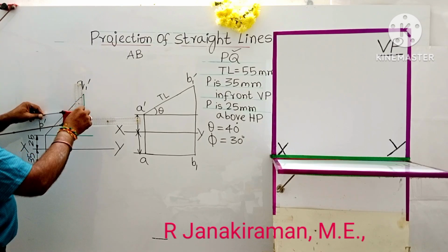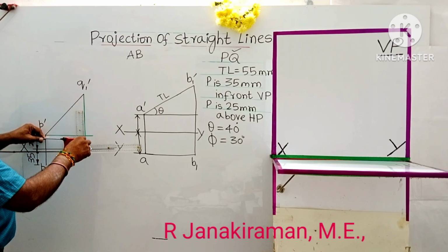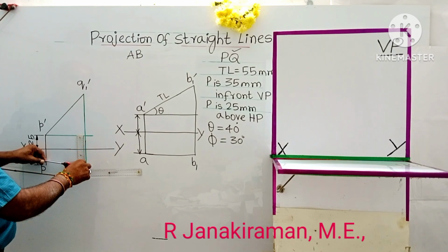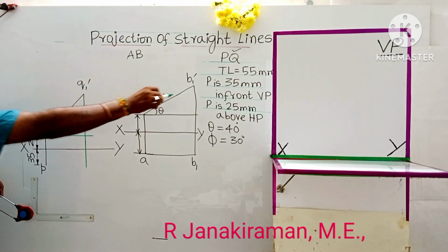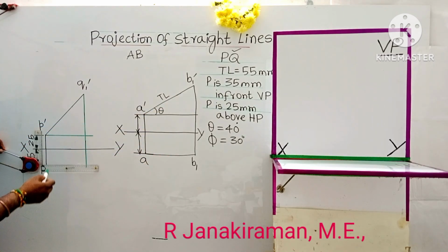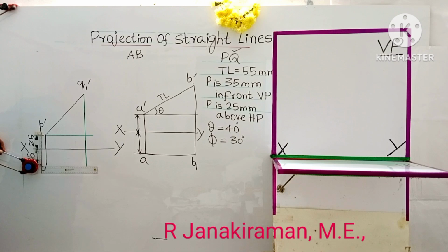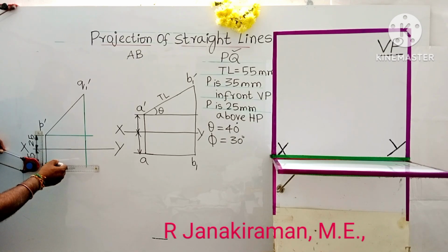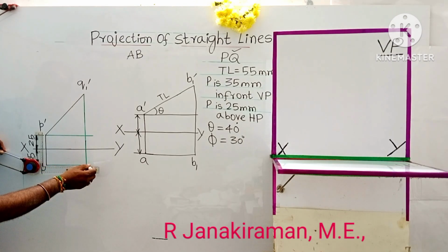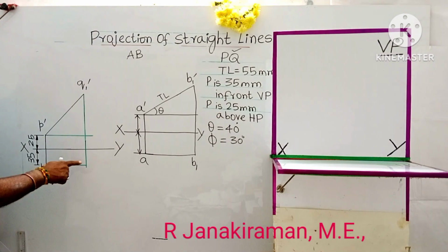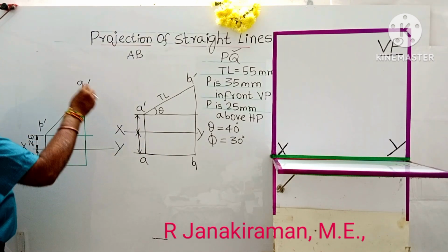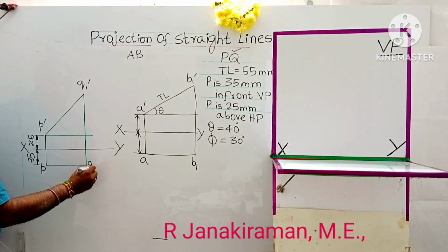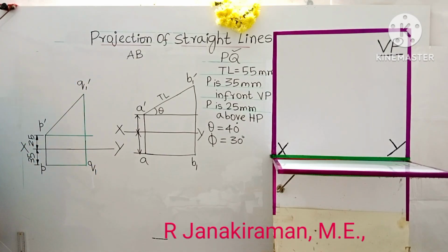So draw a vertical projector using a 2H pencil. 2H pencil gives a lighter line called the projection line, drawn using the vertical scale of a drafter. So this is called the projector or projection line from Q1 dash. This is that line. Then you draw a horizontal line passing through point P. So this point of intersection shall be marked as B suffix 1, here Q suffix 1. Understood?